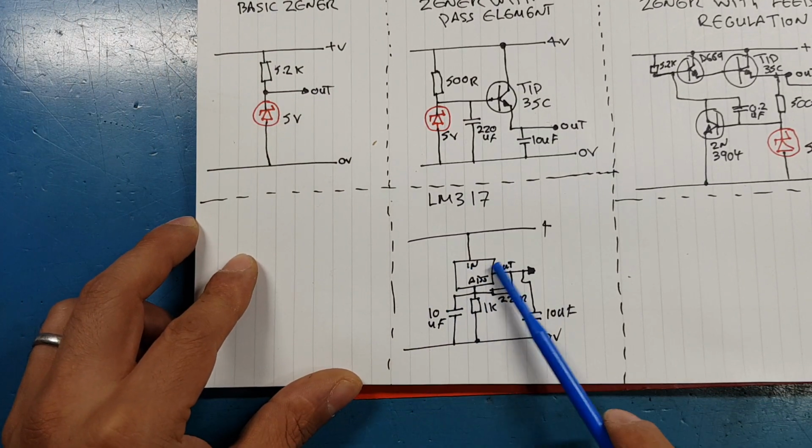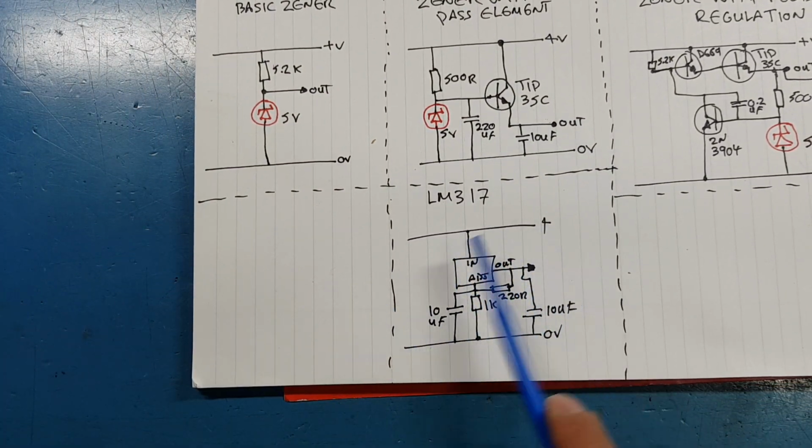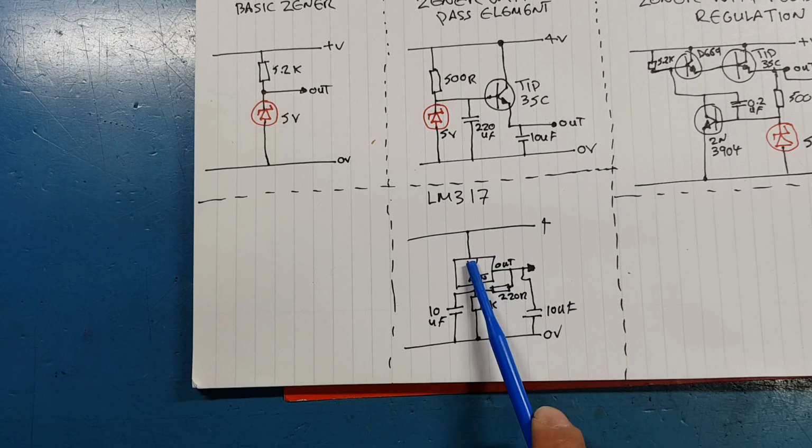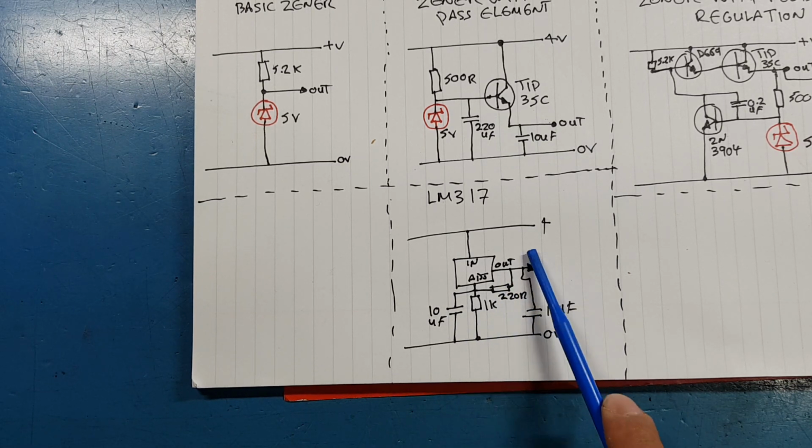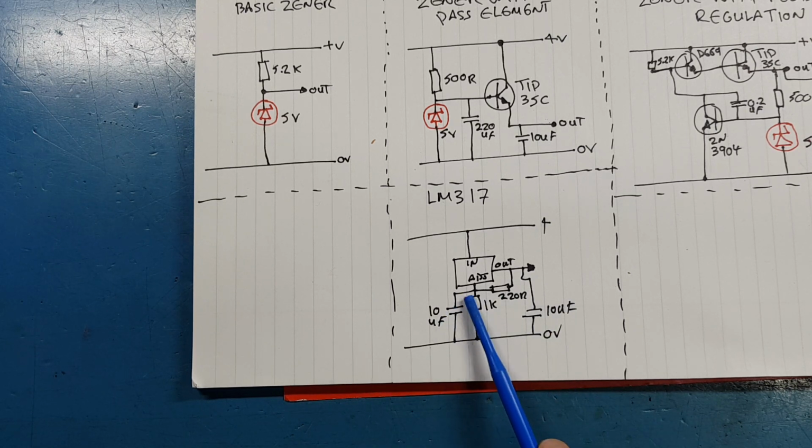And then obviously we have our LM317, which everyone should know about. You have Vin, the set voltage pin, and a voltage divider to set the output voltage. We have a minimum load, because these voltage regulators require a minimum load to function correctly. Usually it's either 120R, 220R or 240R, depending on your circuit. We have our output capacitor again, and a capacitor on the adjust pin to kill any noise and ripple there as well.